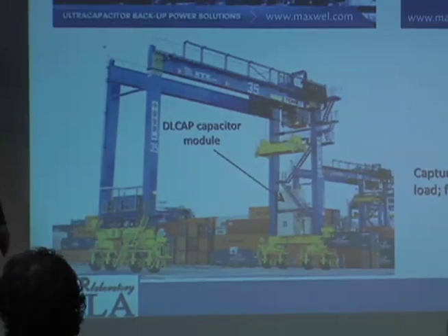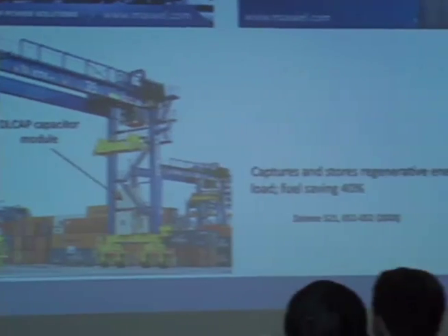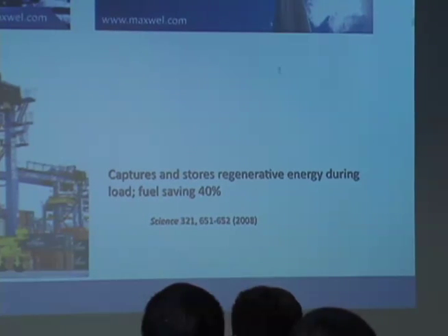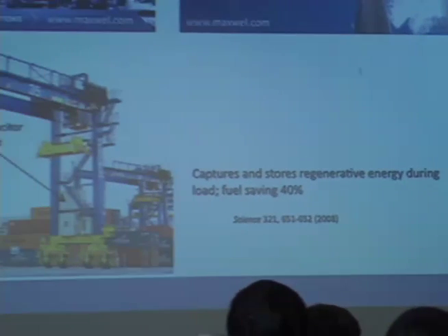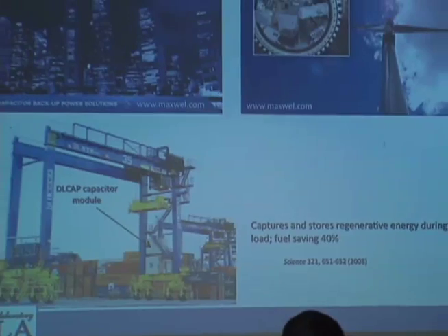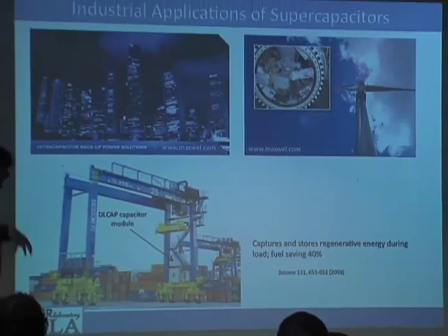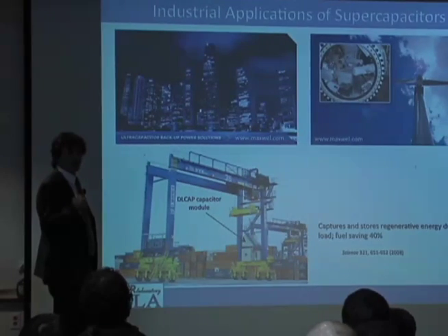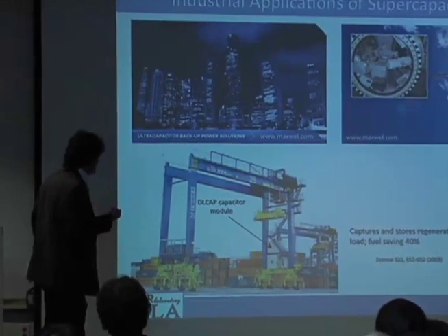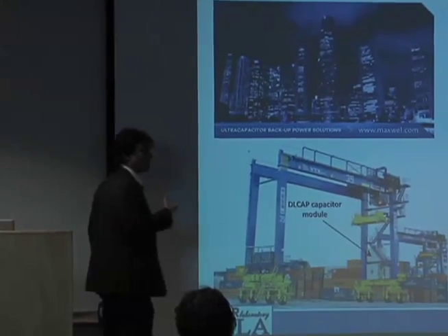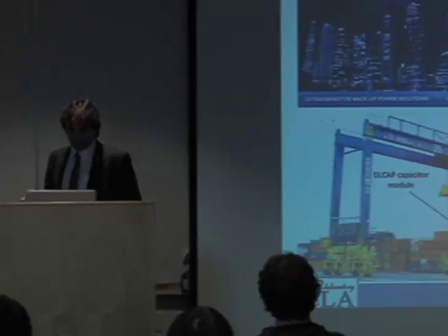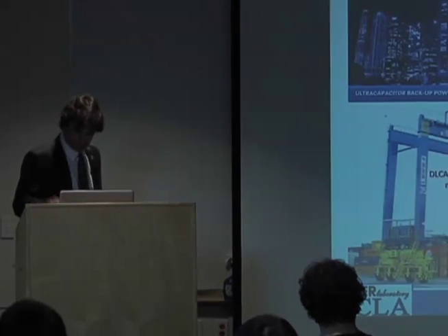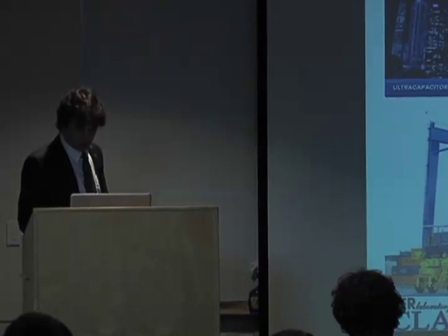It turns out if you go to Japan today, all their ports are using supercapacitors because when you load a thing on a ship, you know, when you pick it up, it takes a lot of energy. When you drop it back down, if you have a supercapacitor, you can recover 40% of the energy. A battery can't do that because the time constant takes too long. So supercapacitors are going in, and the ports in LA and Long Beach will have to do this soon because it's basically free energy once you pay for the infrastructure.